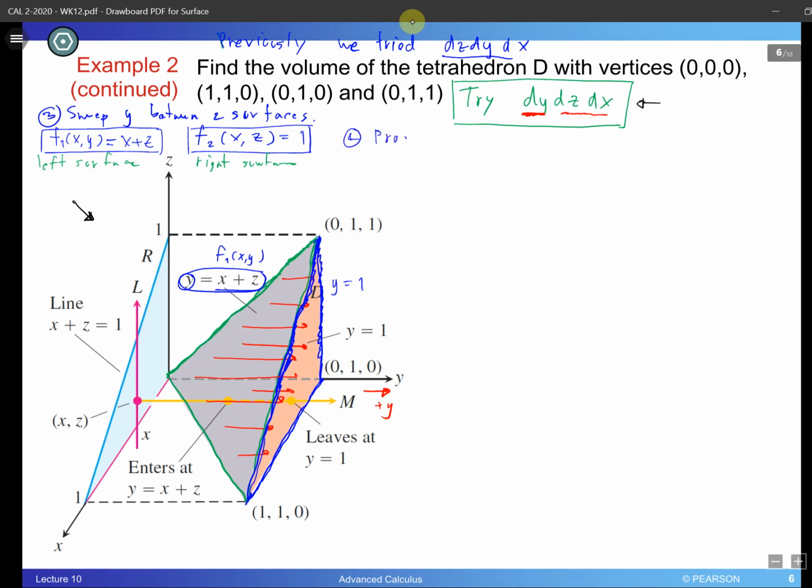Projection on xz plane, and it's right here, z right here and x right here. So in order to find the projection, we are going to put a light source up here. With this light source, you are going to create this shadow of this object, and it looks something like this on the xz plane. It's going to be this shadow with the shape of a triangle.